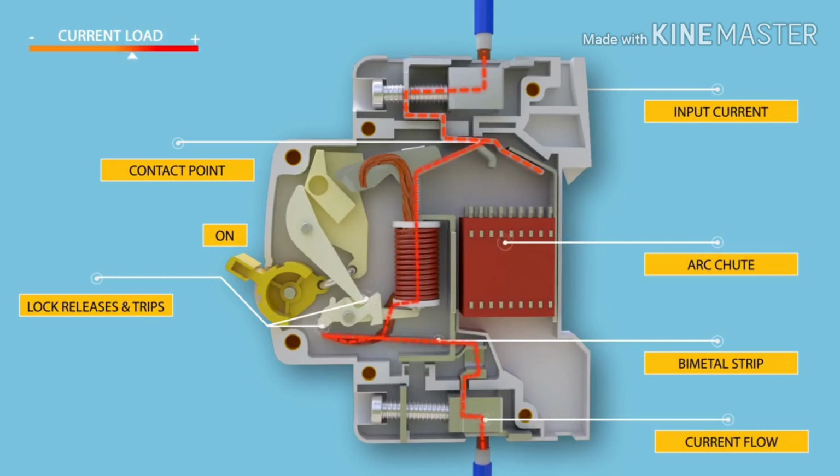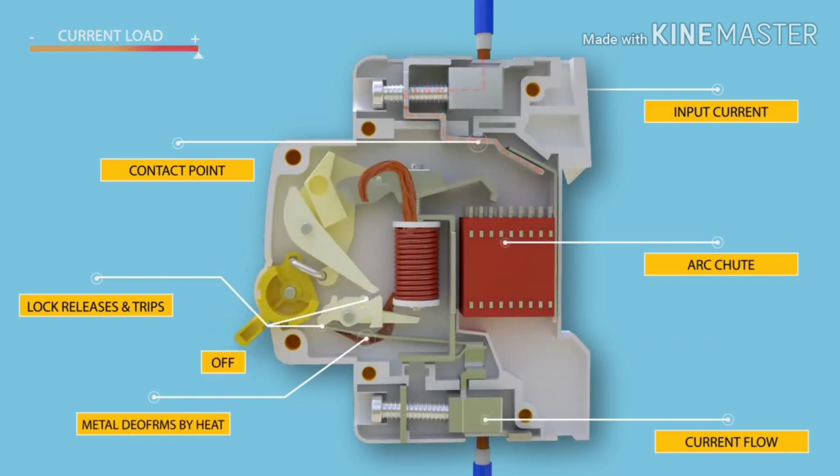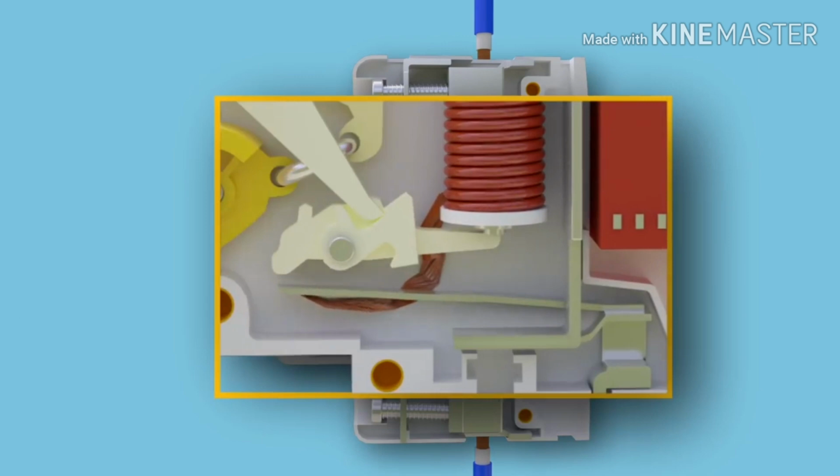In tripping operations, an arc is formed when the contacts start separating. This arc is then forced into arc chute plates, where the arc is split into a series of arcs and at the same time energy is extracted and it cools. Closer look how tripping mechanism works.